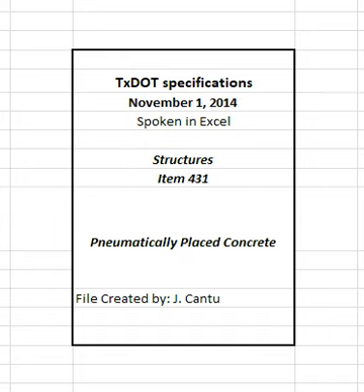Mix concrete sufficiently dry so it will not sag or fall from vertical or inclined surfaces or separate in horizontal work. Prepare test panels using the same air pressure, nozzle tip, and position to be used for the production work to verify the mix design before approval. Apply a 3 inches layer of concrete to a plywood sheet with minimum dimensions of 18 inches x 18 inches for each test panel. Cure the test panels in the same manner as the proposed work. Take 3 cores, each 2 inches in diameter, out of each test panel and test in compression at 7 days in accordance with TEX 424A.